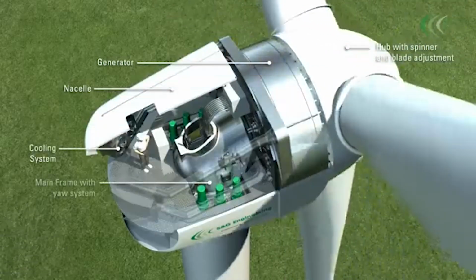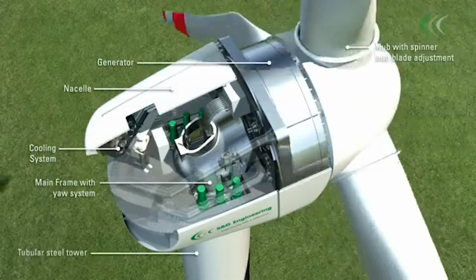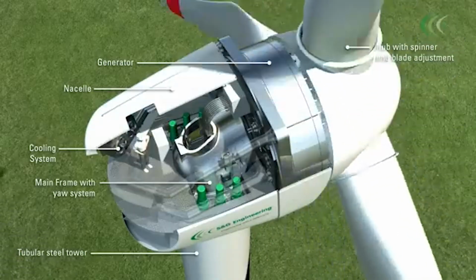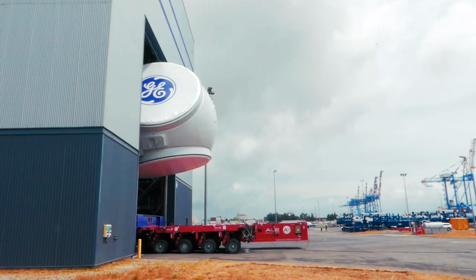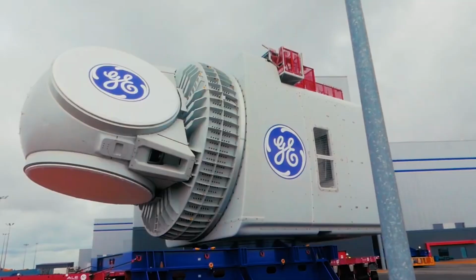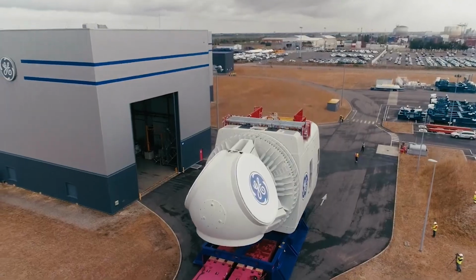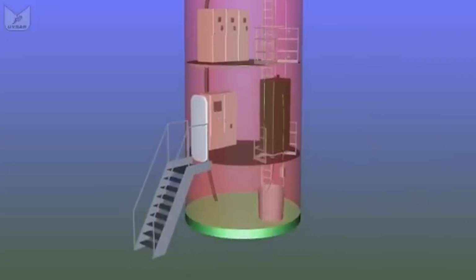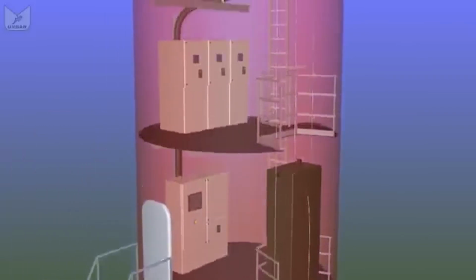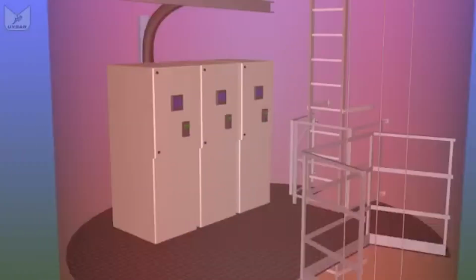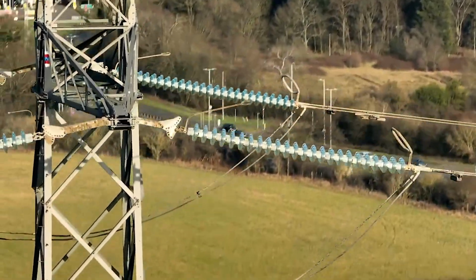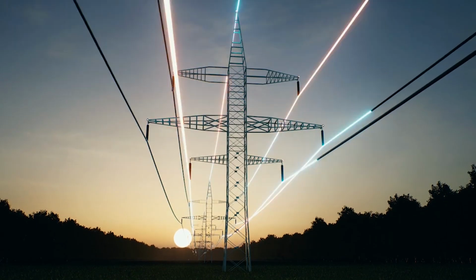The gearbox is one of the more costly and heavily weighted parts of the wind turbine. Thus, new kinds of generators, known as direct drive generators, have come to market recently. These generators are directly attached to the rotor and produce electricity at much lower speeds, eliminating the need for a gearbox. Lastly, the electrical systems and cabinets are made up of transformers and electrical wires. The electricity from the generators is carried down to a transmission substation via electrical wires.